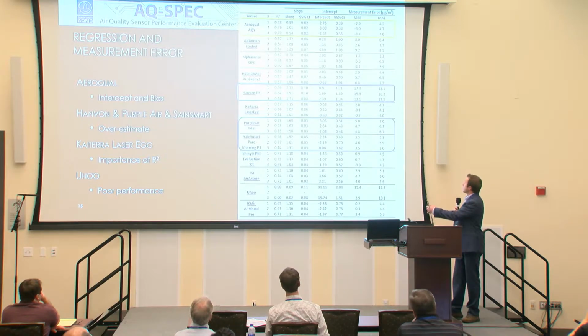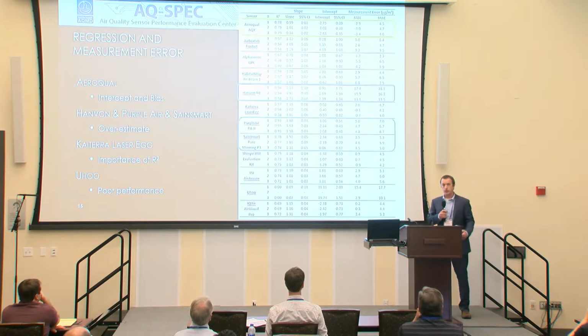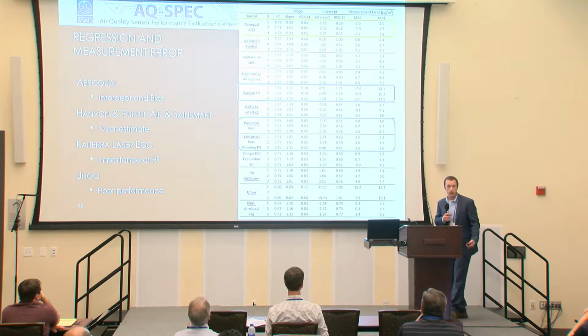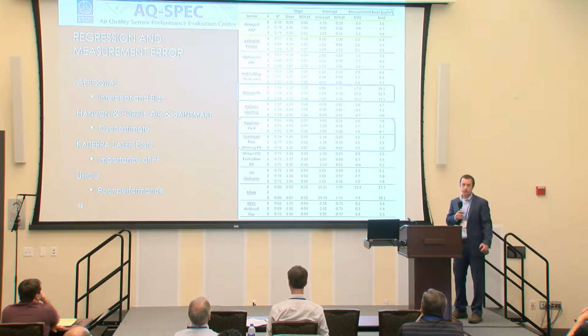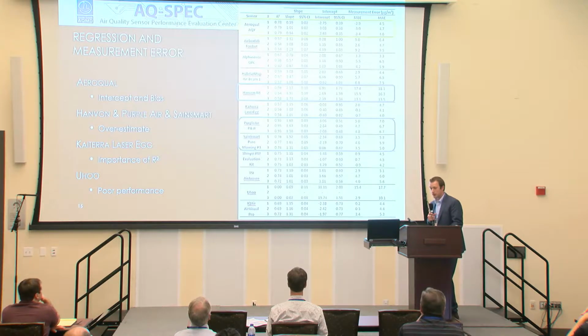You will notice, though, that the bias errors are high. These ones in the 17s, 5s, 3s are typically a good portion of the absolute error. So you could potentially get rid of that bias error with ordinary least squares regression calibrations, and you could get a large percentage of that bias out, but you would still have some measurement error.